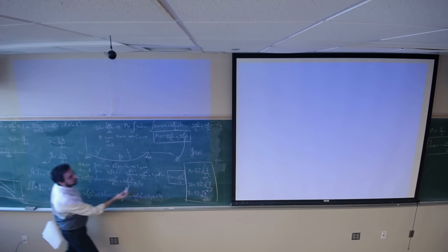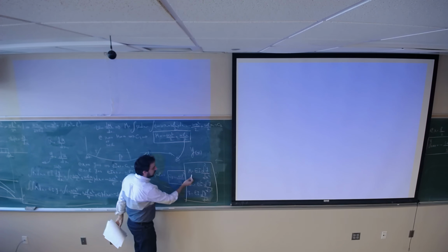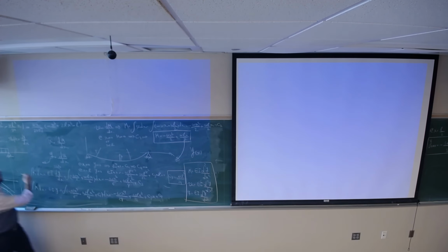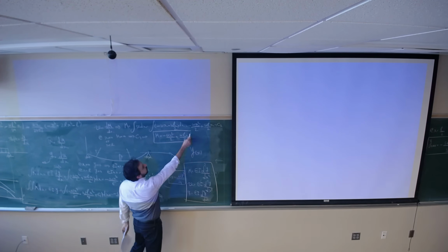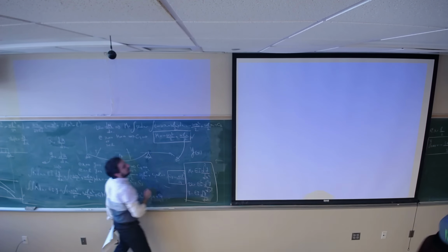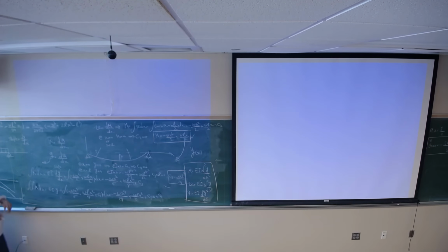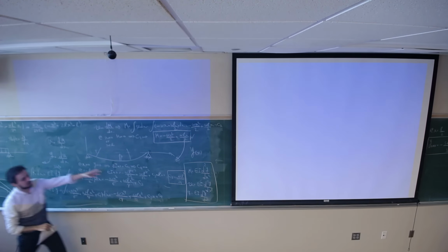For any different loading, what you need to do is find M. If I gave you another type of beam, you need to find the bending moment diagram. Basically, you need to find this equation. After you find the bending moment equation, you can start from this equation.